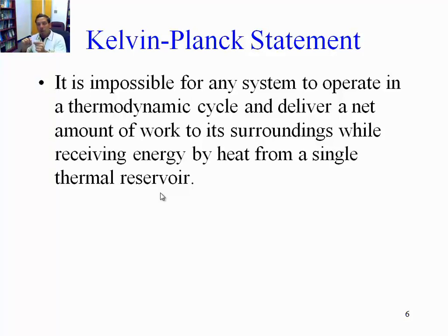Now, in order for you to create a positive net amount of work out of that cycle, the working fluid in that system needs to exchange energy, at least energy in the form of heat, with at least 2 thermal reservoirs, not only with one. Which means that at some point during the cycle it has to absorb energy, maybe from a fuel, burning fuel, and at some point in the cycle it has to reject energy, maybe to the atmosphere.